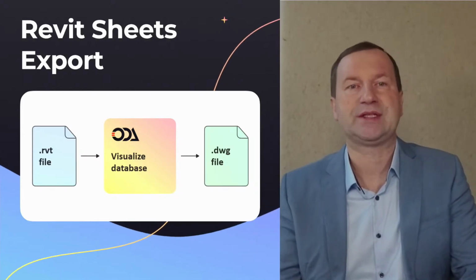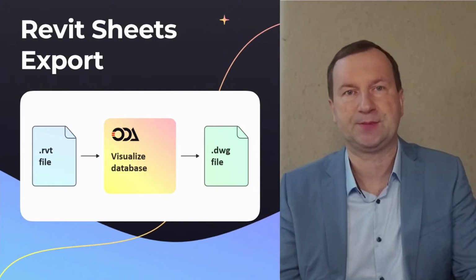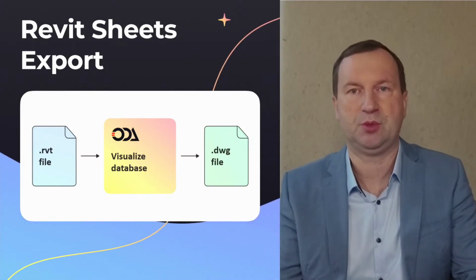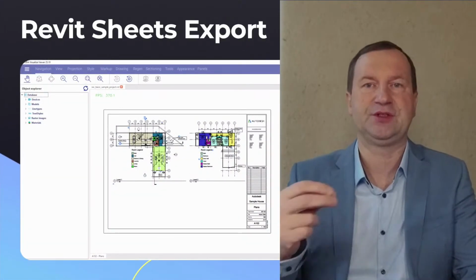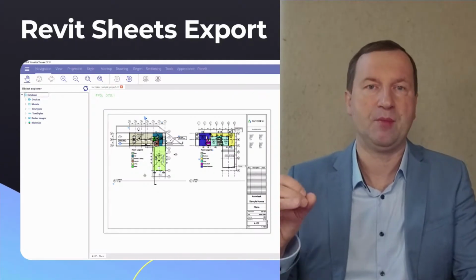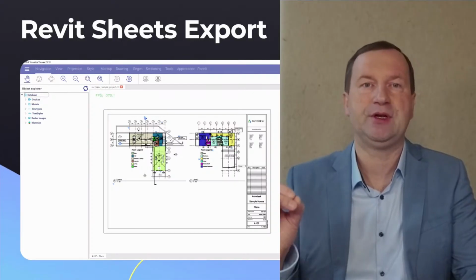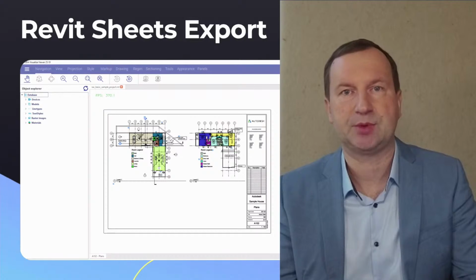However, this task was not straightforward, as it required significant extension to the export from Visualize to DWG module. Initially, this module only supported export to model space. As mentioned, Revit sheets are similar to DWG paper spaces and contain multiple viewports, which were not supported in the original Visualize to DWG export.